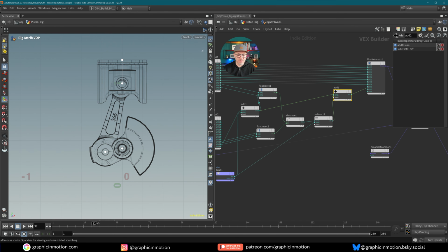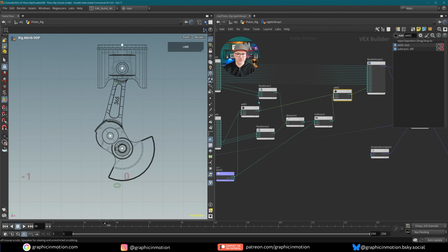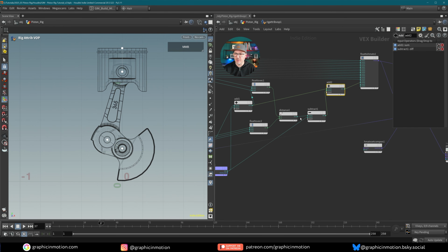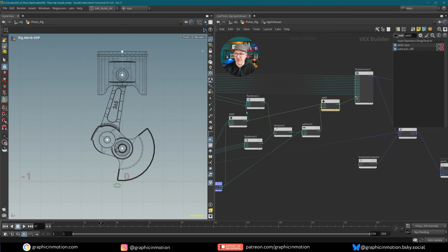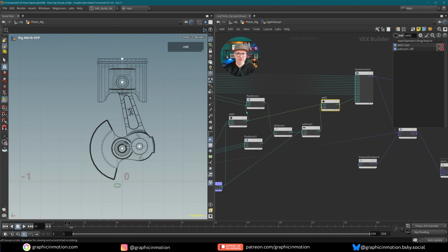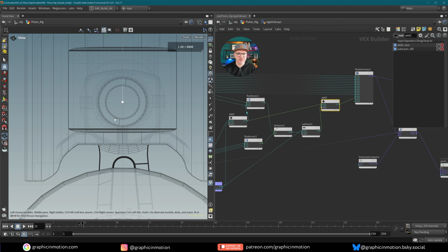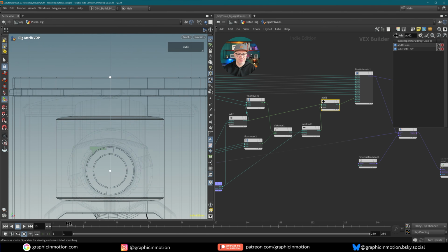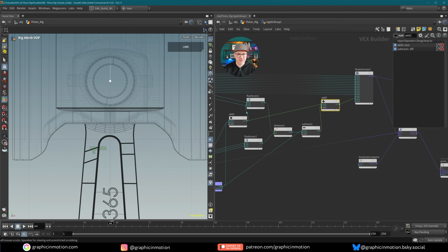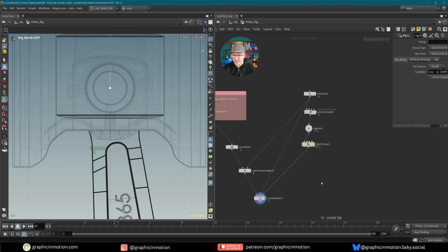And this was probably the wrong way around now, because now I actually have a bigger offset. So maybe I made this wrong. So let's take a look whether I can just reconnect these. Yeah, this was the wrong way. So I have to subtract the moving distance from our fixed distance and then add the correction value in here. And now you see that this is working. And if you take a look now very closely, then there's really no offset anymore. So this now really stays in place and is moving nicely around this joint here. Good.